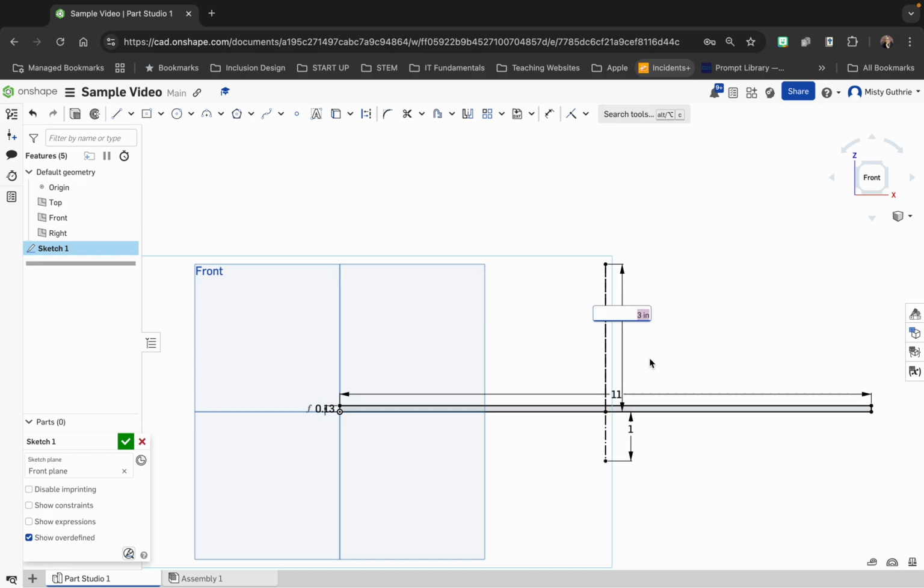So in doing so, we can actually just say, let's say we want to make this an 1/8 of an inch shorter. CAD is really cool because you don't have to necessarily do the math. You can put in the equation. So maybe I want to take off an 1/8 of an inch to allow another stick of balsa up at the top. So if I put in 3 inches and take away that 1/8 of an inch, hit enter, and it will automatically do the math for you. And you could do the same thing on the bottom.